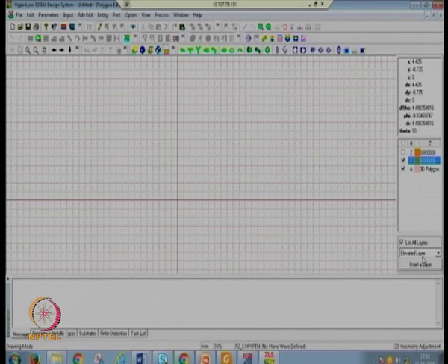In this section you can check different types of layers, like in elevated mode, whatever layer you have selected will be shown on the top and the other layers will be shown on the bottom, but in the actual scenario they will be on the top, in whatever way you design. Now if you do not want to show the other layers, if you just want to show only the layer which you have selected, then you select this option, or if you want to show other layers in the form of contour, then you can select those things. So in this way you can proceed.